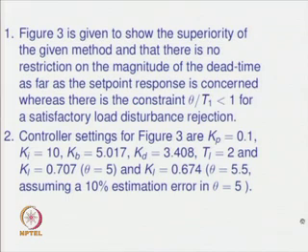What we have done basically, why are there two thetas here? Now, we have assumed a 10% estimation error in theta. You are using some estimation technique. Suppose the time delay is estimated erroneously, there is an estimation error of 10% in the estimation of time delay, then it can go to a value of theta equal to 4.5 or a value of 5.5 depending on underestimation error or overestimation error.